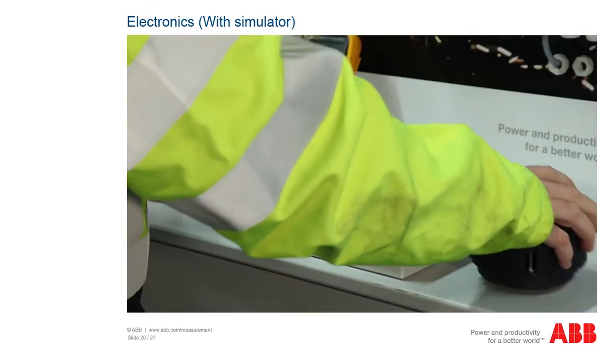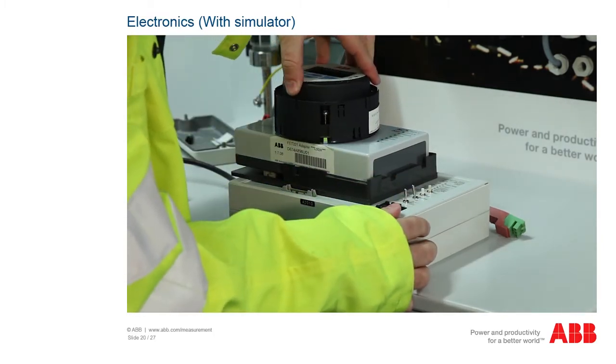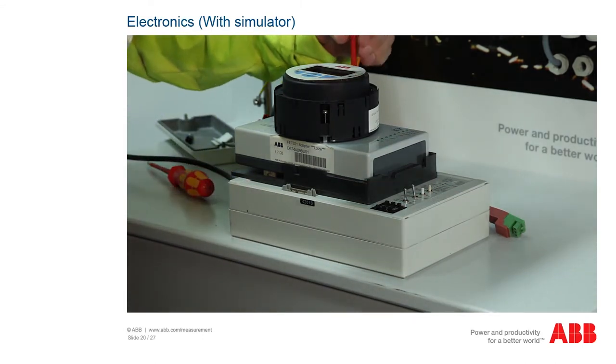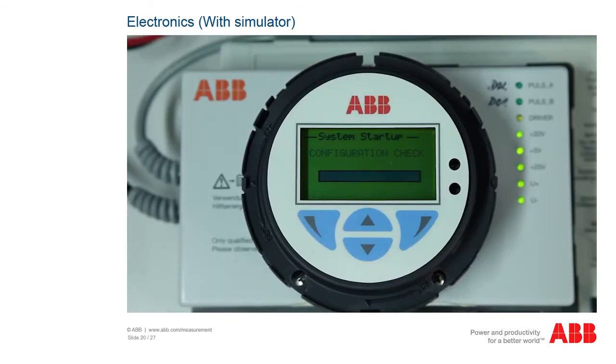Now use the flow meter sensor simulator to test the transmitter. To do this, place the flow meter sensor on the simulator. Make sure that you do not bend any contact pins. Screw the flow meter sensor on tightly with the 3 screws. Now switch the simulator on.